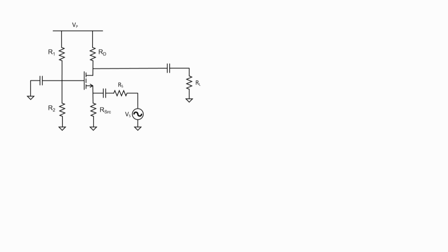We're going to need a small signal model for the MOSFET. In other words, I want to replace the MOSFET with some equivalent circuit that's easier to analyze. It has 3 connections at the gate, the drain, and the source. Here's how we're going to model it. We'll assume that the MOSFET itself has an infinite input impedance. Since the gate's electrically isolated from the source and the drain, the leakage current, or the parasitic leakage, is usually really small. So this is a very realistic assumption to make.